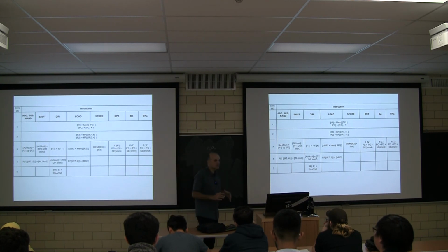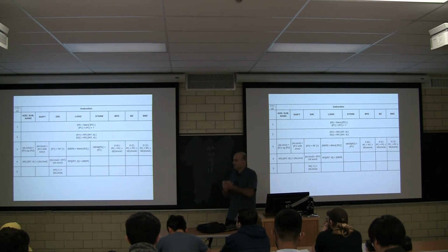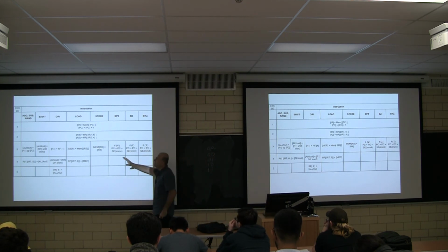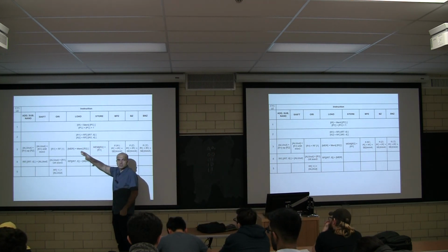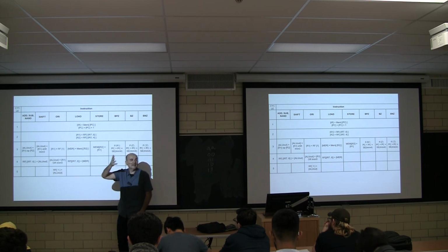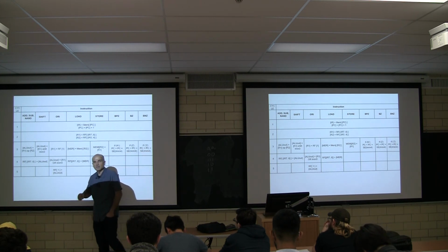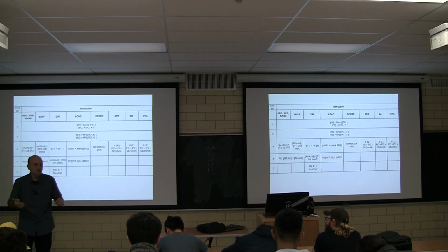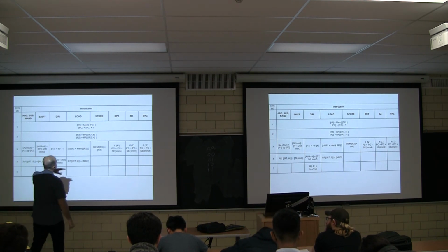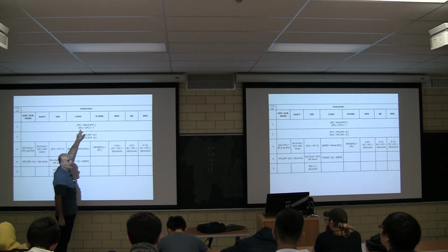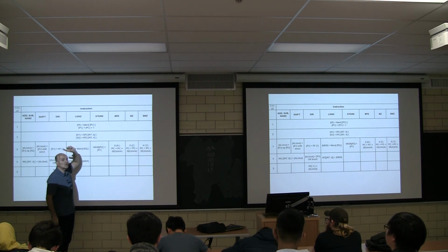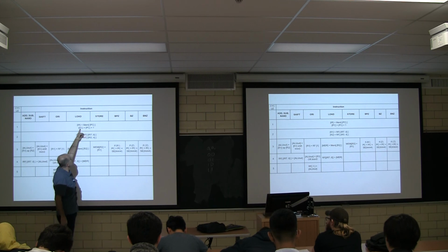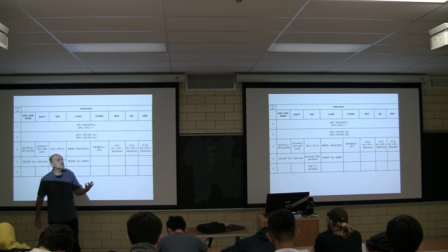And we're first going to do the add. And before I show you the circuit, let's look at what this thing says. This is supposed to be a register transfer language. That's the term people use. It's called RTL, affectionately. This is the acronym. If you look at every box, it has a left and right hand side. It's an assignment. You have some values you read, and then some storage elements you're changing. Some of those storage elements are visible to the programmer, like the program counter. Some of them are internal, and they're only visible to the implementation.